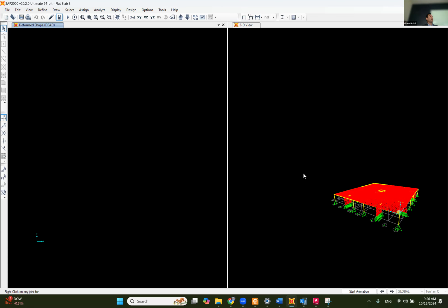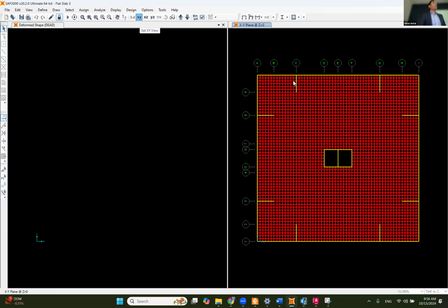But sometimes they make the shear walls first. In most modern construction right now, they make the shear walls first, because there's a way that you can construct the shear walls fast. And then at the location of the connection with the slab, they put the reinforcement, but then they bend it and cover it somehow, and they leave this area ready to be connected with the slab. So once you come to the floor that you have the slab in, there's a way to do it.